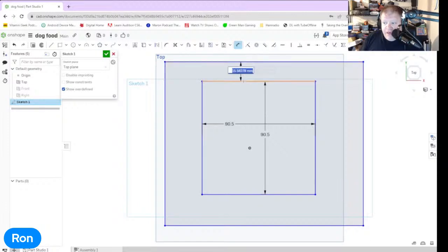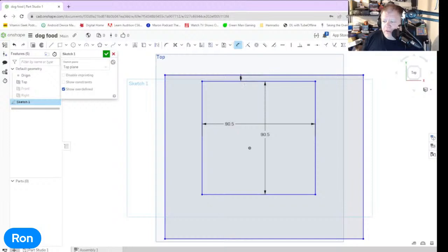Yeah, let's make that only 5 millimeters across. Okay, dimensions. Down here to here. Come on, dimension tool, stay on. Sometimes Onshape is really picky at times. Well, that's really high. That's not good. I'm going to set that for 5.